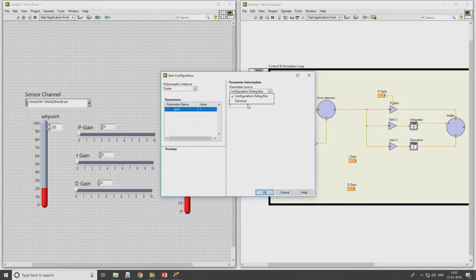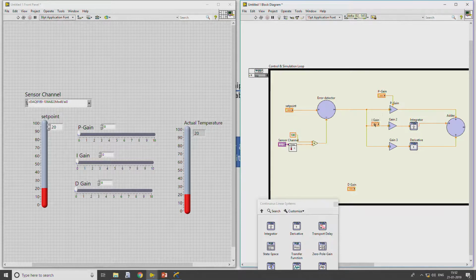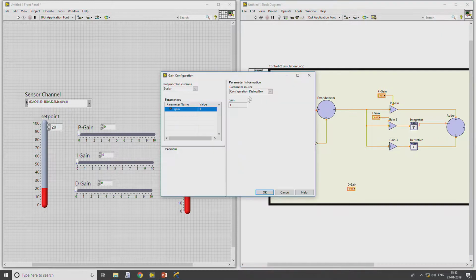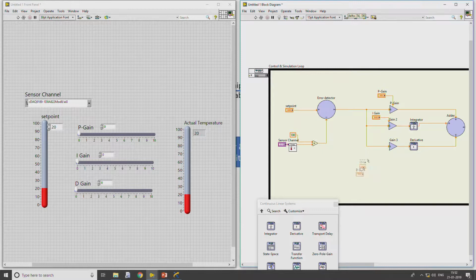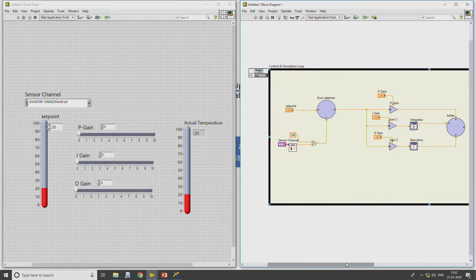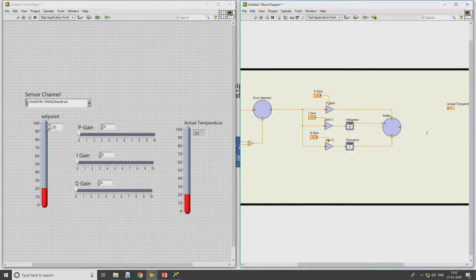So with this we can easily create P as well as PI, as well as simple I, or a combination of P and I, or a combination of P, I and D. But we cannot use a simple D controller, because when the error is constant, the derivative gain will become 0, so the output given by the controller will always be 0, right.